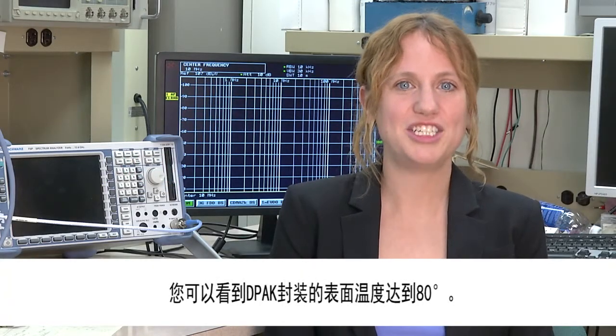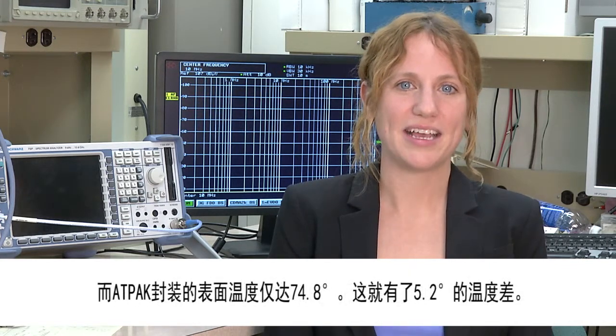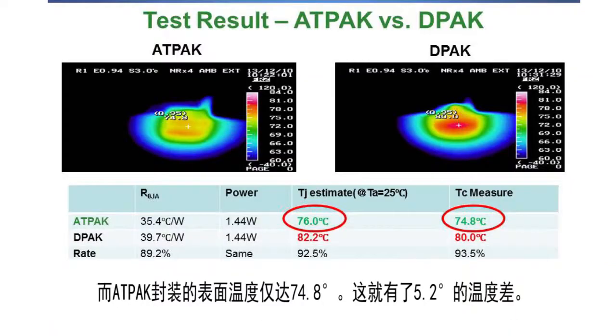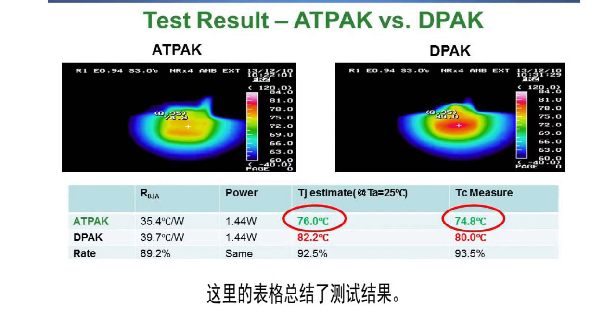You see that the surface temperature of the D-Pak package reached 80 degrees, whereas the surface temperature of the Atpak package reached only 74.8 degrees. This is a temperature difference of 5.2 degrees. If we estimate the junction temperature based on the thermal resistance, our calculation shows that the gap was approximately 6.2 degrees, which validated the test result. The table here summarizes the test result.